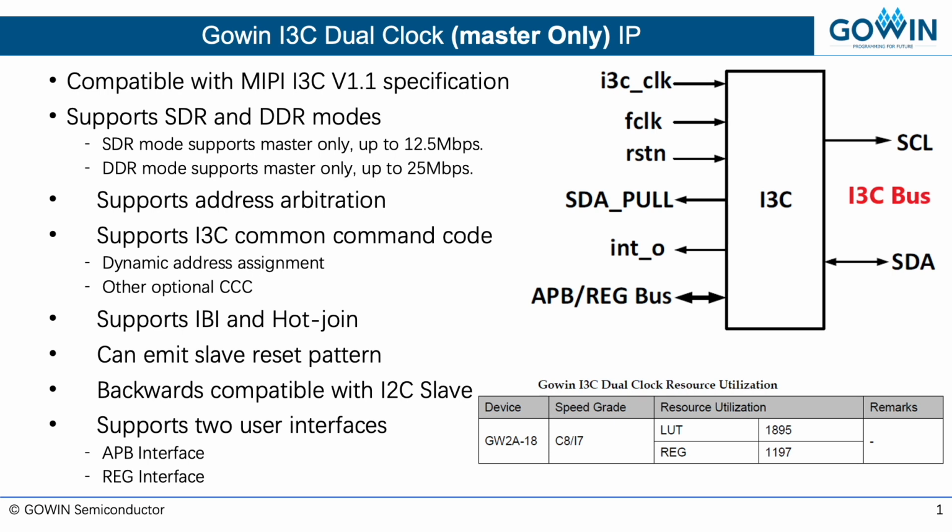In addition to the FCLK into the IP, we have another clock called I3C_CLK. The FCLK is slow and is used to do the register read and write operations. And the I3C_CLK is fast and it is used to generate SCL and can go up to 100 MHz. The ratio of I3C CLK to FCLK must be 2:3 for normal I3C communications.